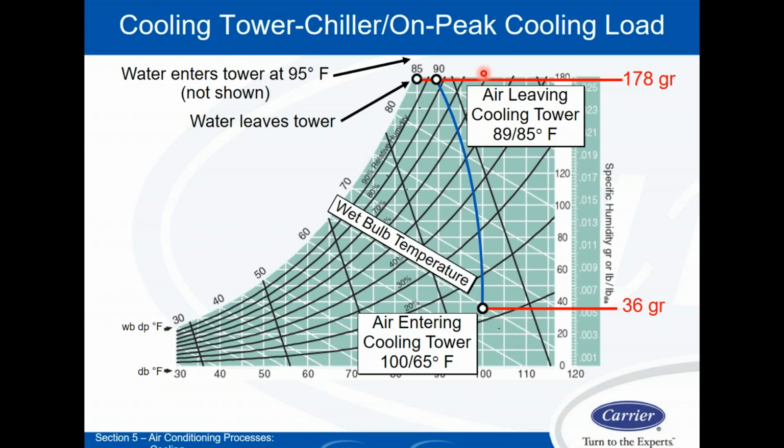That's why the moisture content is in fact going up. I'm also getting that evaporative cooling effect. That's why I'm going from right to left, so I have kind of a curved line going up. I added a lot of moisture in this case to get a very small amount of cooling, getting 10 degrees of cooling by adding a ton of moisture.